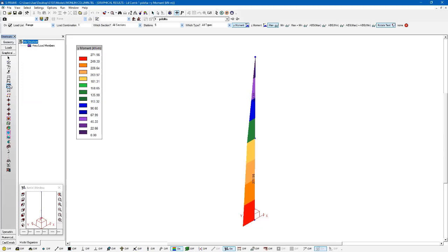If I were to then go up to 500 load increments, am I going to notice a major change in results? Well, the reality is that the more load increments we use, the more accurate our analysis results will be. But at a certain point, they're going to converge. And it's up to us to decide when that point is. If you have the time, I certainly recommend going through different numbers of load increments to see if it's going to converge at whatever value you predict it to be.